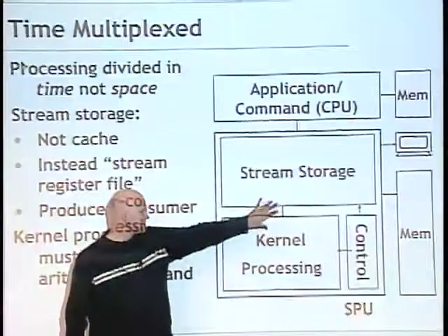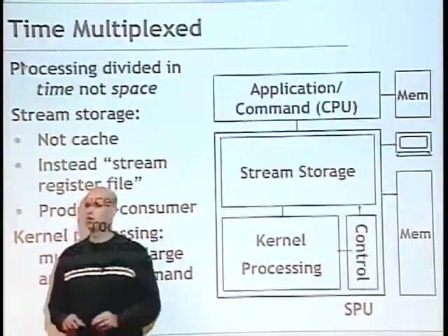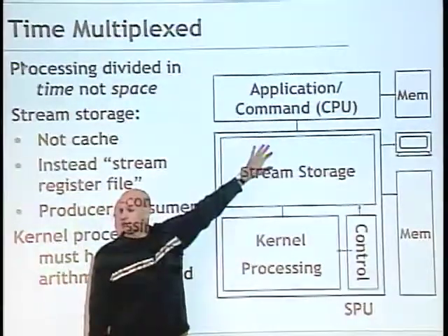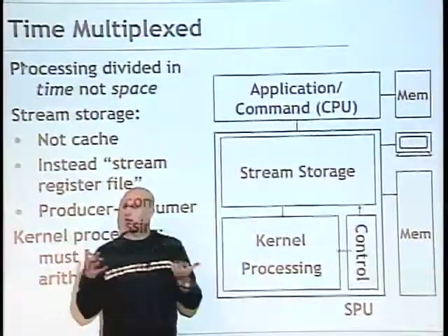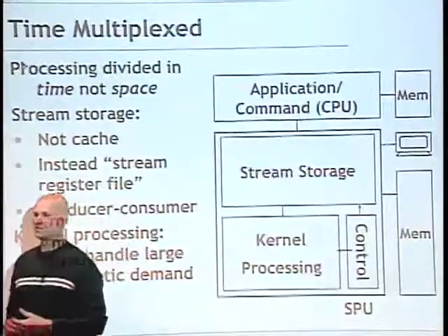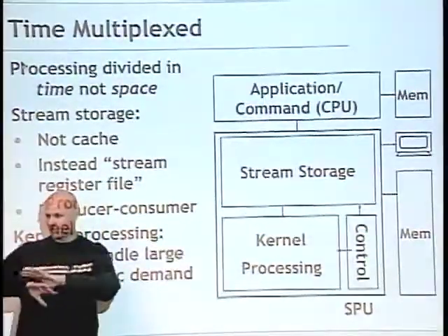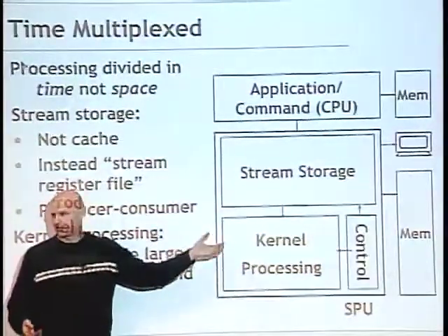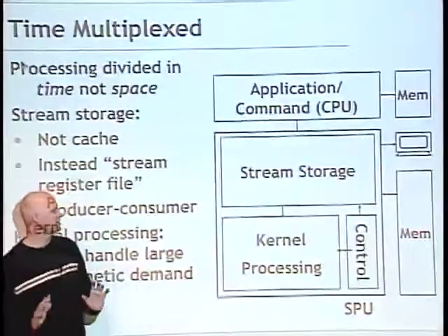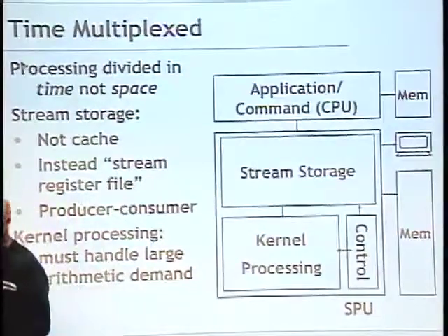So the nice part is that the bandwidth you can get on chip is generally very high. So roughly, if we say the bandwidth from here to here is X, okay? So off-chip bandwidth is X. Then global on-chip bandwidth is generally on the order of 10 times X. And local on-chip bandwidth, like where you're just communicating with your neighbor over all the kernel processors where you presumably do work, that's like 100 times X. Okay? So the nice part is if you manage it nicely, you can get 10 times the bandwidth you'd get if you had to go off chip for it.